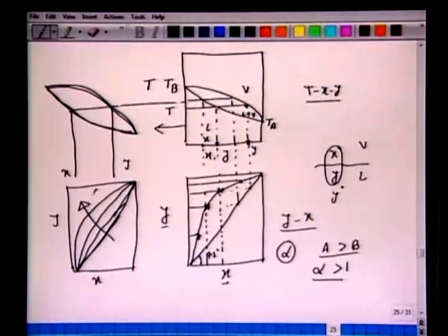Here what we have done is increase the relative volatility. The farther you are from the 45-degree line, the larger y is, so y1 is greater than y2 greater than y3 for the same x. So we have plotted the yx diagram for different relative volatility.